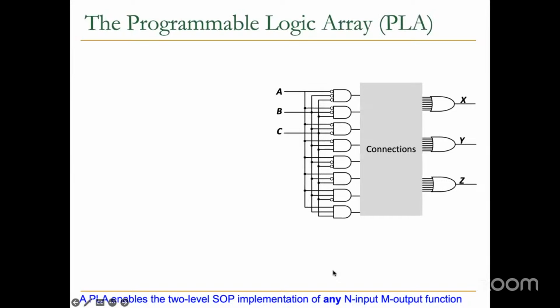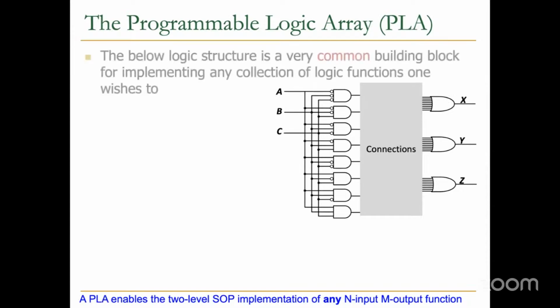Okay, so basically, you can program these connections over here. Actually, you don't have programmable connections necessarily here. You could. But in this particular programmable logic array example, you generate all the minterms, and you decide which minterms to connect to the OR gates to specify a function. Okay?